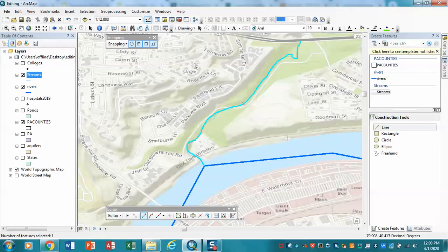I'm going to do it again real quick right here so that you understand how the process works. So I click once, and I simply move the line around, and it creates kind of a sequence of very tightly spaced vertices. Double click again. Now, you'll notice that as I'm doing this, I'm getting this each time. If I click F8 again, now when I digitize, I'm back in the single vertex mode. You can move between single vertex mode and streaming mode by simply clicking the F8 key again, and now holding down my mouse key. I'm back in this. I click F8 again, and now I'm out of it. And so F8 brings you in and out of streaming mode.